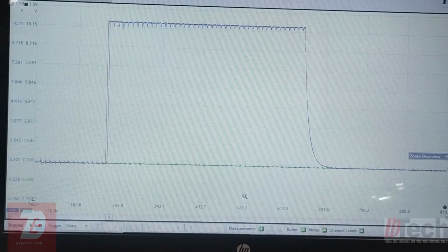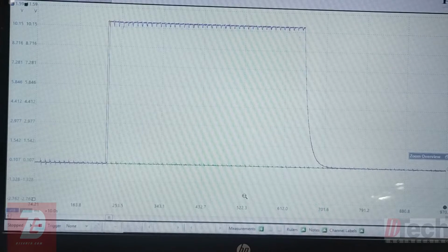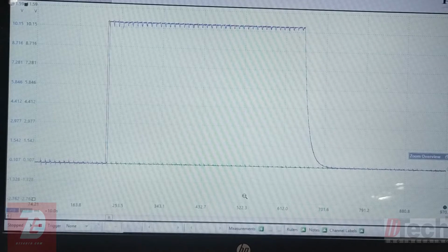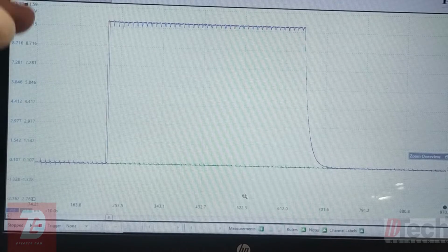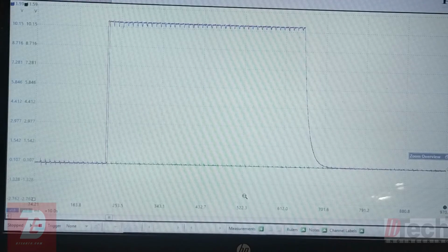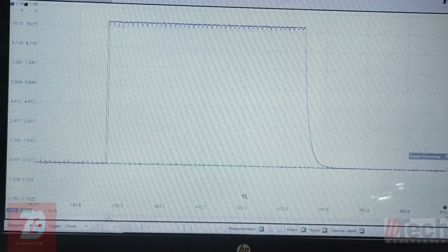Alright. So, before we make an expensive incorrect call of potentially saying the module is faulty and not putting out supply voltage, or it's just pinging on the circuit, let's call it. With both unplugged, it's acting the same way. It'll supply, it'll notice that the circuit is open, and then it cuts off its supply. Both sides are doing the same thing, so I think both sides are good as far as the module.